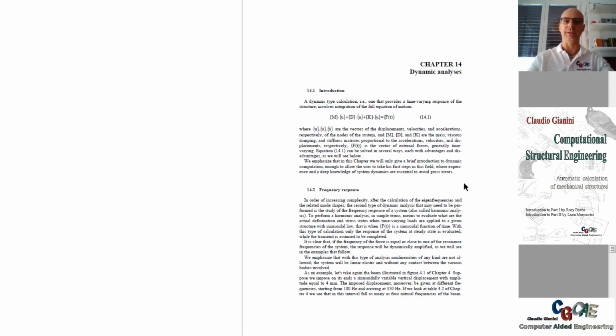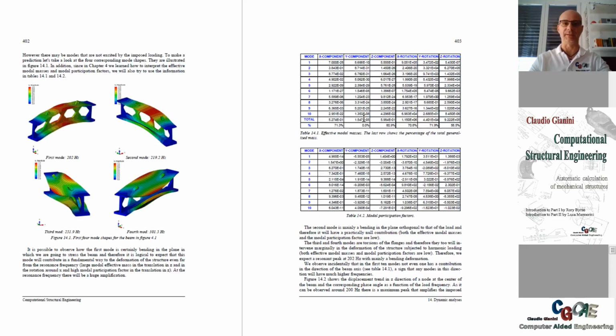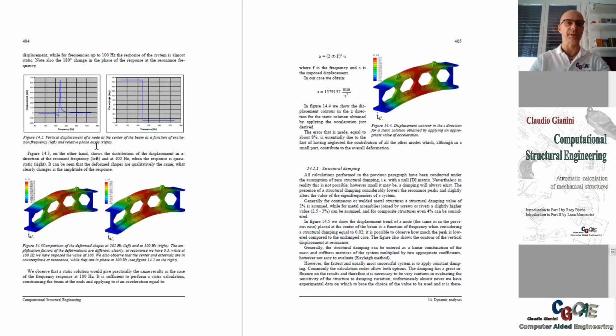So chapter 14 deals with dynamic analysis, meaning not the normal natural frequencies that we have already discussed in chapter 4, but exactly the response of a structure to dynamic force excitation. So we still keep the same example, same beam, loaded in a different way, and we go first of all through the frequency response, where we can then extract by changing the frequency of the forces.